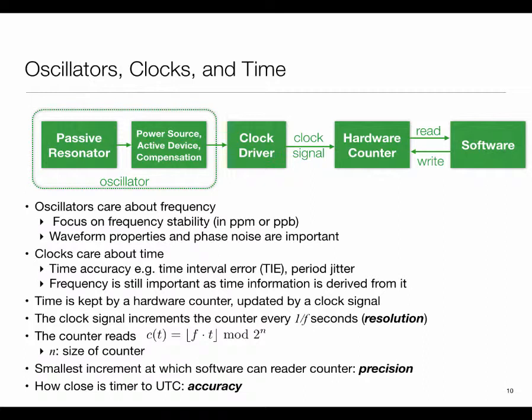They are nothing but an odd number of inverters in a chain, and that oscillates because if you think about it, an odd number of inverters in a chain are going to oscillate. The nice thing is they are built in, they are tiny, they can get very high frequencies. The bad thing is they are very, very unstable. They could be thousands of ppm. Okay, so they are quite unstable, but they power up very rapidly.